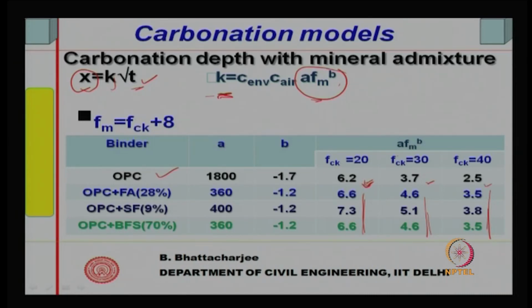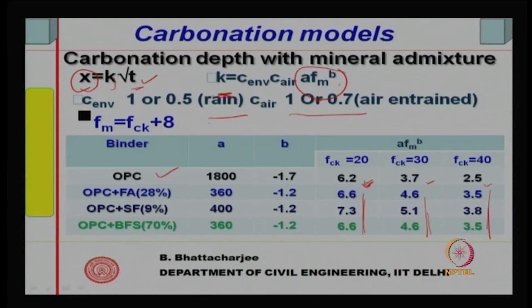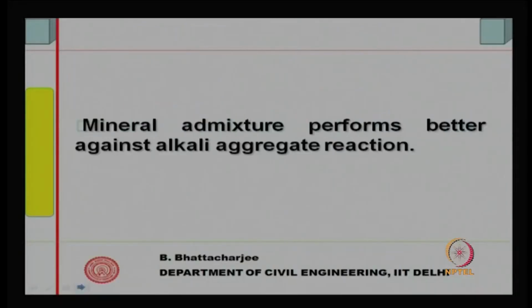So, with mineral admixture carbonation depth increases, the rate of carbonation actually increases, because calcium hydroxide is consumed by them right in the beginning, right. So, these are the other parts of the formula which we might discuss sometime later on when we talk of durability, but carbonation depth increases with addition of mineral admixture. This will be clear when we talk of durability.